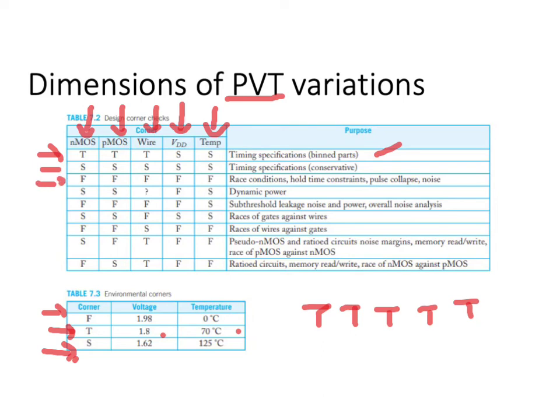So the key takeaway from this is that simulations and design verification at the front-end stage are not only done at the default or anticipated mean operating conditions. They must be simulated for different process, voltage, and temperature corners. These are called PVT corners, to see that if the product, the IC, is operated under different operating conditions or goes through certain variations in the process during manufacturing, a high percentage of the fabricated products would still meet customer specification.